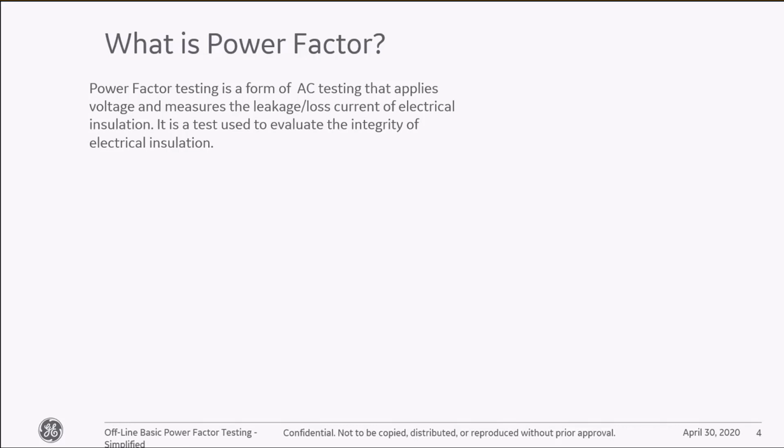That's the one I used because I at least knew that what I was doing was going to tell me something about the insulation. I didn't really understand the number that I was obtaining. I didn't necessarily know what that number represented. I only knew, hey, I should be at about 0.5%. I'm at 2%. There's a problem here, big problem. But if somebody asked me what it was, that was my standard answer. It's a test used, you know, we check the integrity of the insulation on this electrical equipment. But if they pinned me down any further than that, I was probably going to sink.